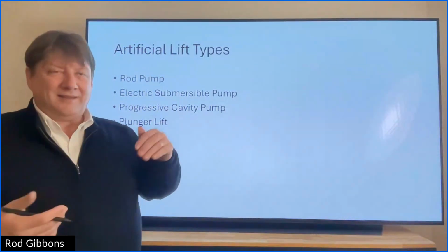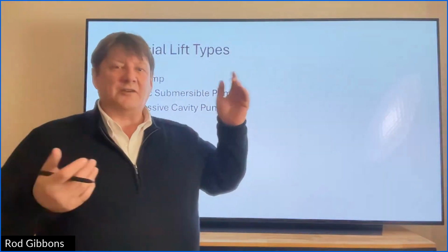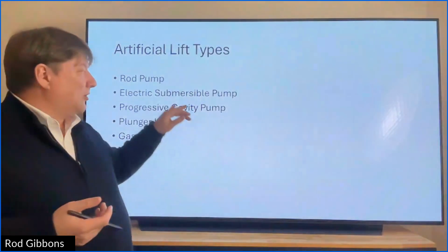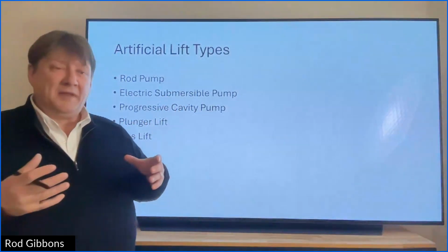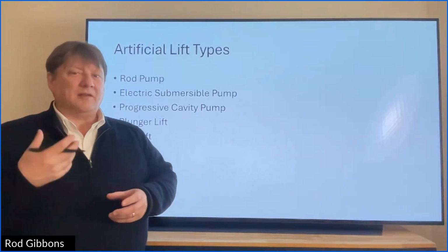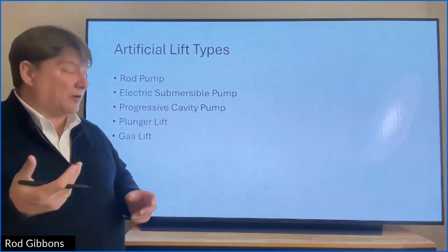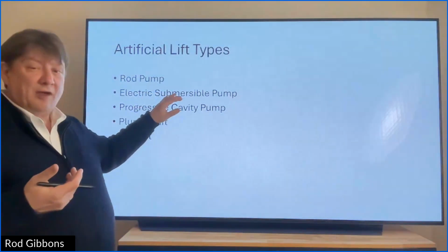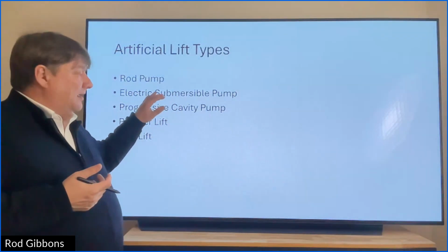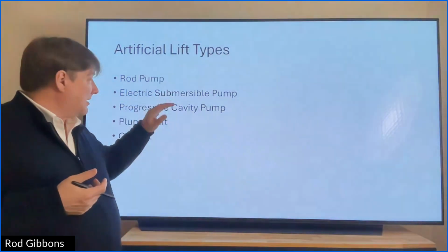And so there gets to be where pump jacks get so large, it's not really practical. Whereas an electric submersible pump, the pump and motor is in the well, and so it can do a lot higher volume rates. So more high volume wells, electric submersible pumps are quite popular.